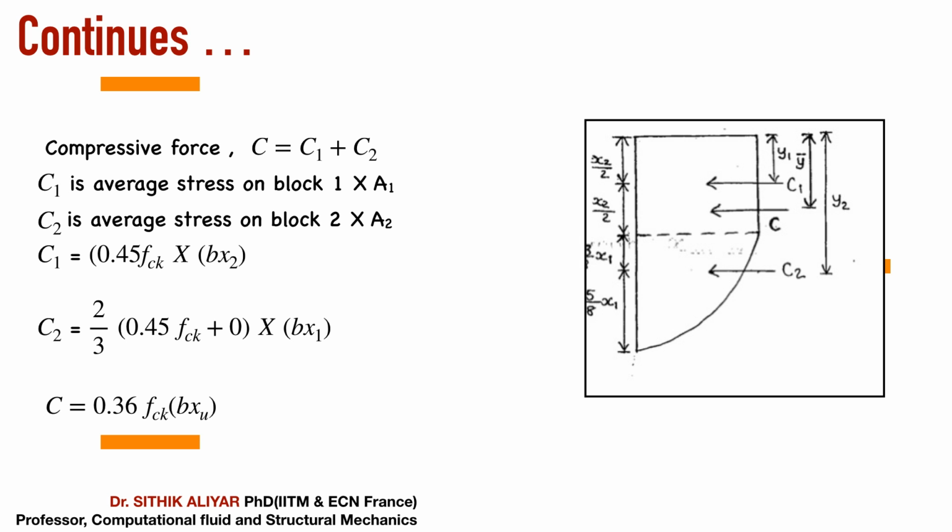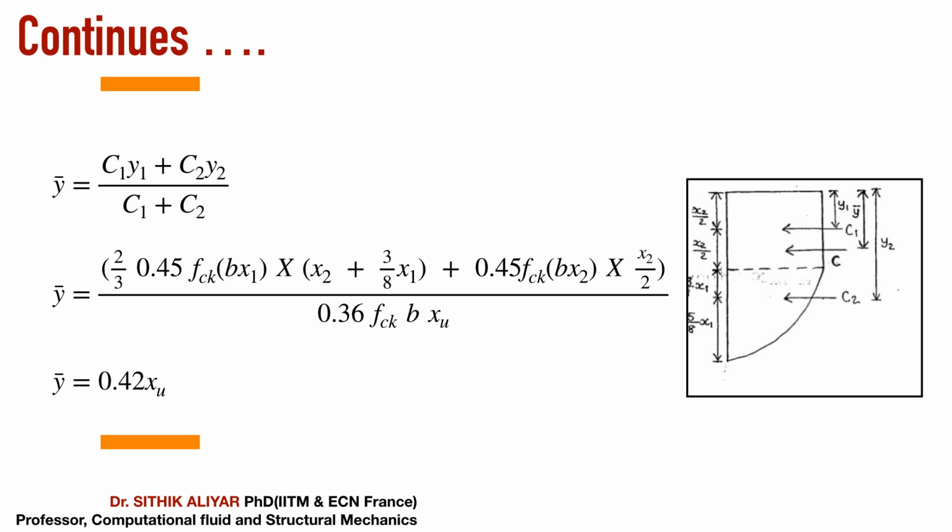Okay, so I hope you are sure that from fck we came to 0.67 fck, from 0.67 we came to 0.45 fck, and from 0.45 how we got to this 0.36 fck. If you didn't understand, please don't go to the next slide. Pause, go through the videos again and again, and try to understand how from fck you reached 0.36, then you can understand the next things. So I hope now you know what the compressive force and the tensile force are.